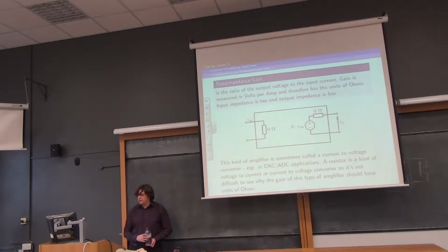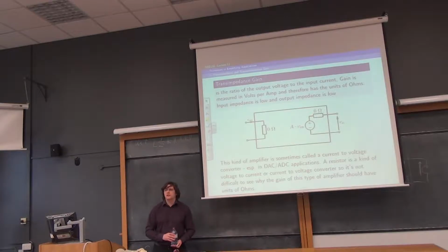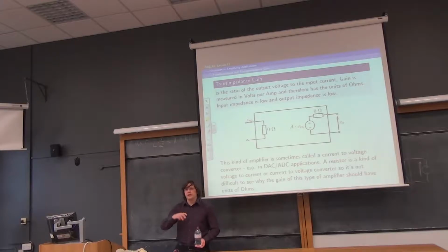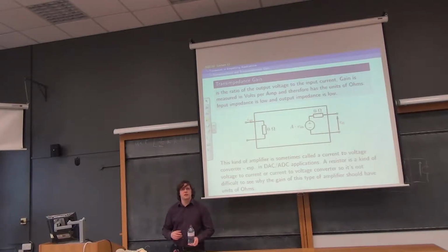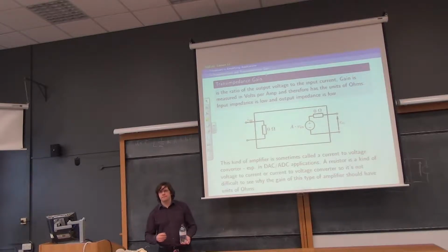And these are often used in fibre optic receiver type front end systems. Usually you'd have some fibre optic cable with some light pulses travelling in them, another form of travelling electromagnetic waves. And you'd have some photodiode or some such where you've got some semiconductor and the light goes in and promotes some electrons, and the electrons do some travelling about in the semiconductor, and then they induce a current in the external circuit.